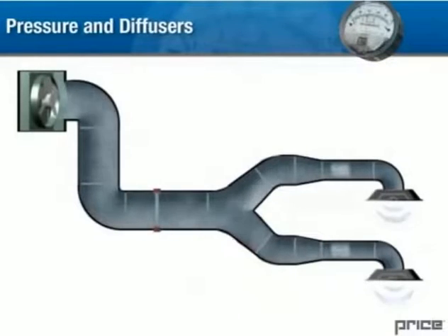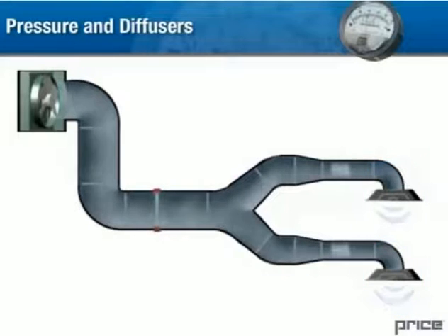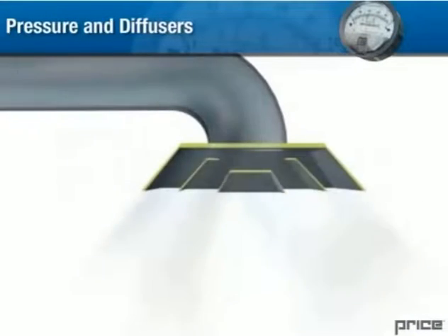In the interest of energy efficiency, we want to deliver air to the environment with the least effort possible. In the best-case scenario, pressure drops in the HVAC system are kept to a minimum. Like all other HVAC components, diffusers should produce very low pressure drops as well. Performance need not be sacrificed to achieve this, since well-designed energy-efficient diffusers, such as Price's SCD line, will still produce optimal air patterns with low pressure drops and low air velocities.